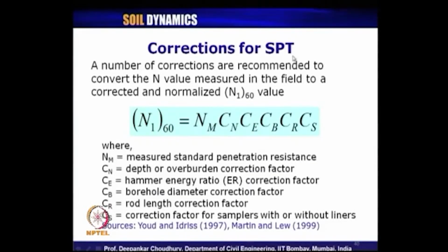Now, what are the corrections for the standard penetration test? I am talking now only about the corrections related to the static test itself, that is the static value. I am not coming into the dynamic or liquefaction aspects. So, remember these are the corrections which you already know. The corrections I am referring to here are worldwide standards; then I will mention what the Indian corrections are, as recommended by our Indian standard design code. A number of corrections are recommended to convert the raw N value measured in the field to a corrected normalized N160 value.